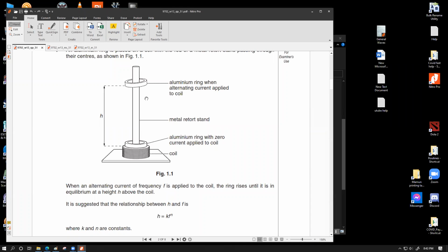And a safety precaution for this experiment can be that the current produced in the coil should not be too high, so that it doesn't heat up too much. The possibility of burns can prove to be a difficult thing. To do this experiment, essentially we have to keep this coil energized, or fed with current, for a significant amount of time, at least let's say 1 minute or so, for taking one full reading, to take the height measurement around the whole thing. So this coil has to deal with a significant amount of current for a significant duration of time.